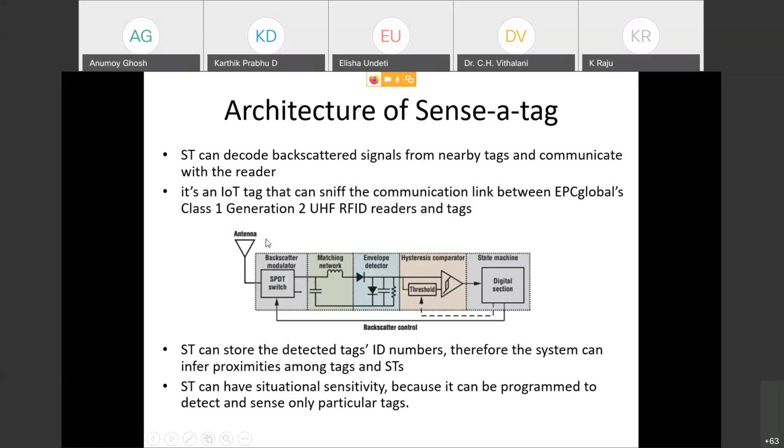Now, in general, since I am dealing with cars which are coming to a very close distance to each other, I go for amplitude modulation. I don't go for frequency modulation or other techniques, because amplitude modulation will be enough for this kind of signal. Here I'm not giving out other digital information. For example, in a toll tax, you are giving out digital information about the registration number and so on. But here I'm not giving out any digital information. I'm just giving out information about how close I am. So for that, an amplitude modulation technique is much easier.